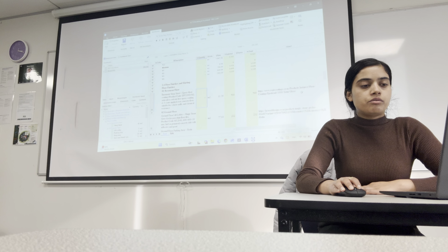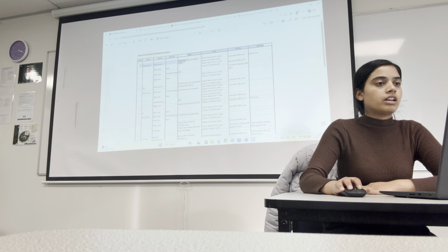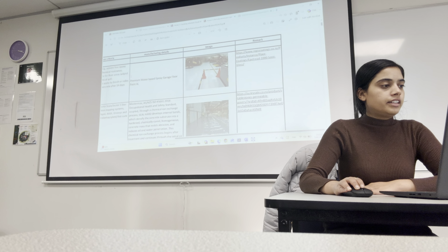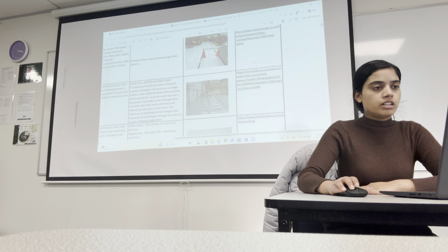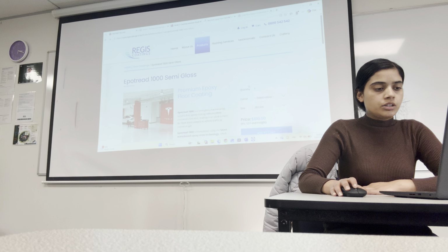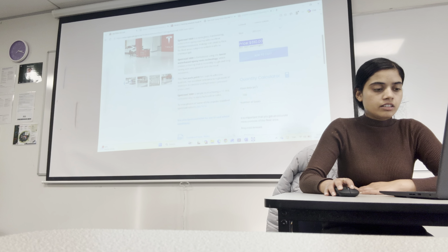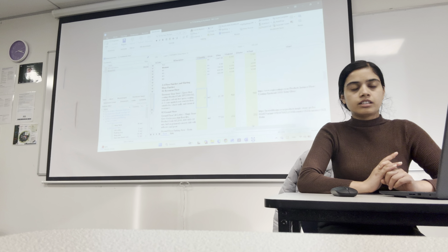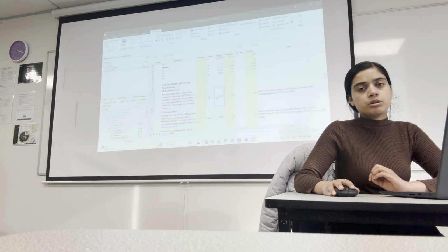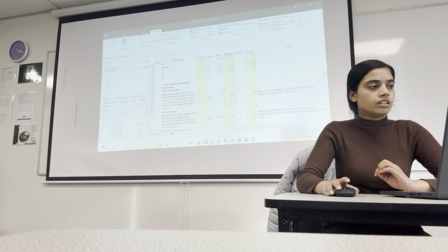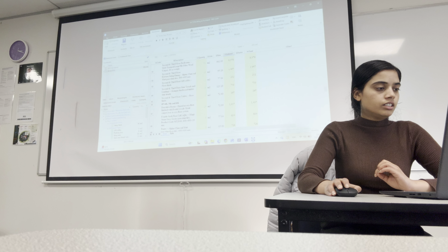For the shop area, as you know, the shop area is epoxy painting or cement mortar, so I have used my third annexes. In the third annexes, we can see the epoxy painting. We can see one link from here. I click the link and I know the quantity, the size and the price from here. So I calculate everything from here, and I have also added the material, plant, and labor cost, as well as overhead and profit cost in here. I calculate it as $11.39 per meter square, and I multiply the quantity with the rate, and I find my subtotal and total from here.